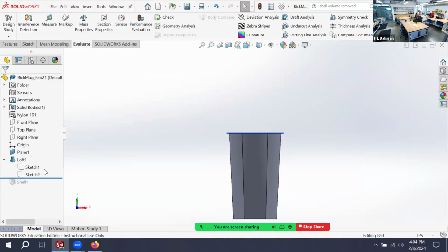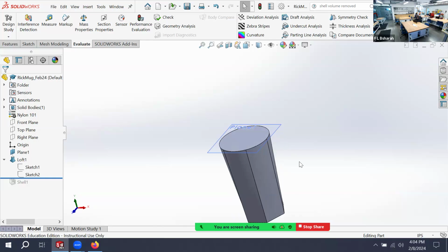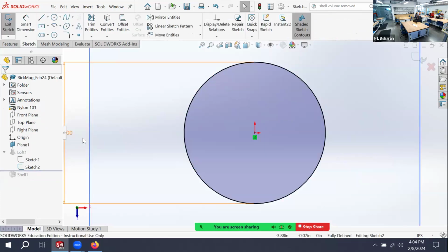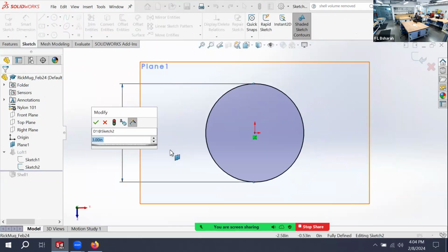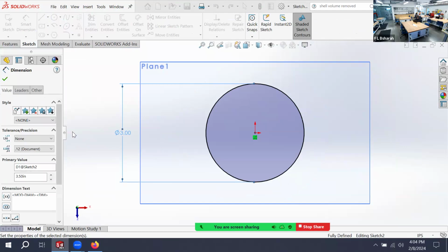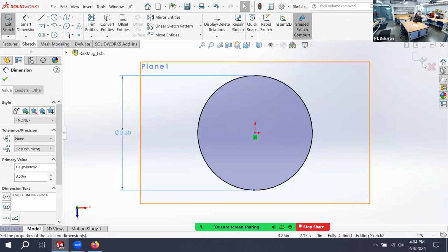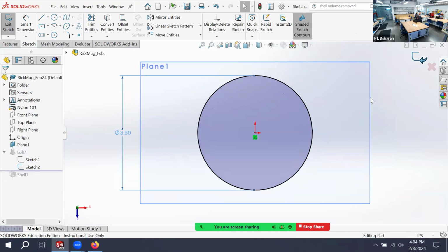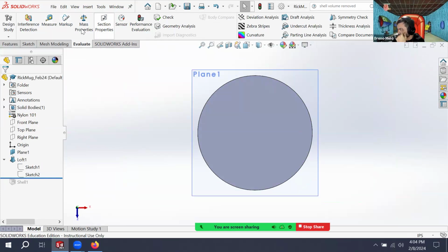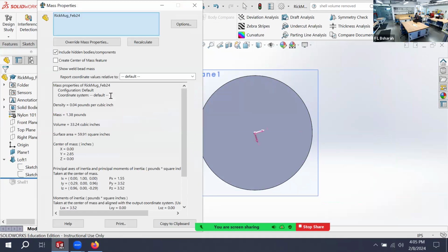Okay. We have room. Aesthetically, I like my mug, but I could like it equally well with the top a little bit bigger. But 3.5, and that'll get me close to 30. Hopefully it'll be more like 33 or 34. I say okay. But you still need to shell the mug, right? I do need to shell. That's why I'm saying now it's 33.24. So I write that number down.